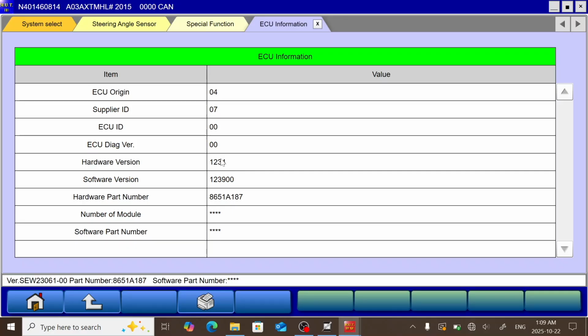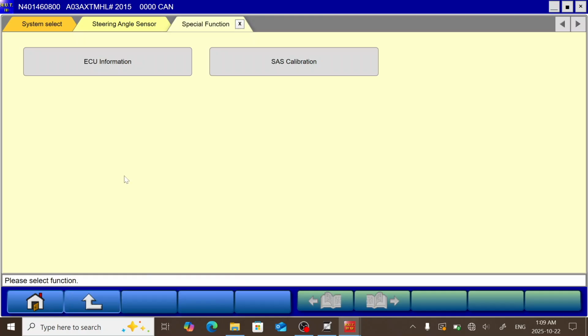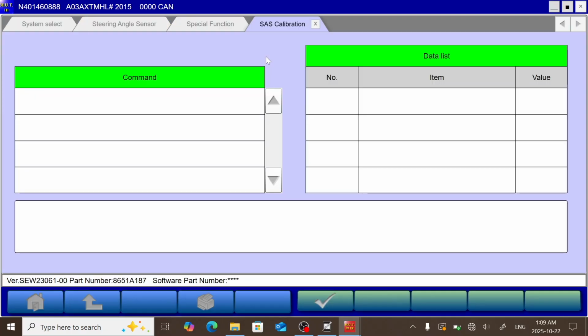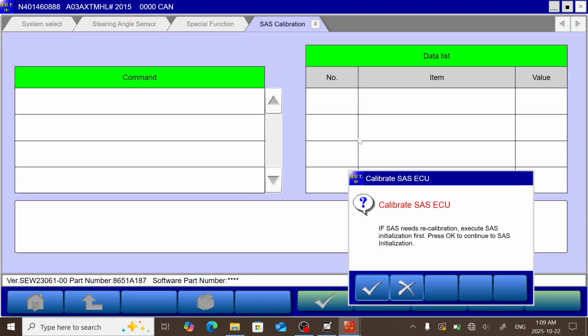Power steering is purely based on vehicle speed, engine RPM, and the torque you're applying to the steering wheel. There are no driver assistance aids like lane trace assist or lane centering assist, where it would need to know the steering angle and then turn the wheel for you. And you can calibrate the steering angle sensor. We're not going to try this, no.